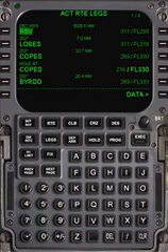From the cockpit, the FMS is normally controlled through a Control Display Unit (CDU), which incorporates a small screen and keyboard or touchscreen. The FMS sends the flight plan for display to the Electronic Flight Instrument System (EFIS), Navigation Display (ND), or Multifunction Display (MFD).